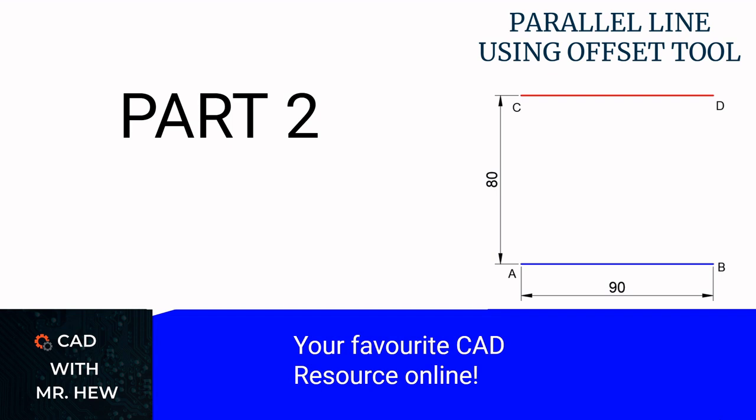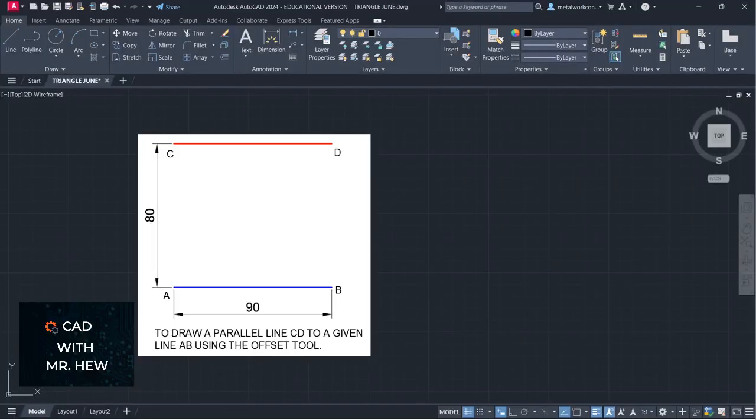We'll be starting part 2, and we'll be looking at how do we draw a parallel line using the offset tool. We'll be starting the video now. All right, so we'll be looking at the second method to draw a parallel line. So we're going to start off with our line. We're going to turn on snap and ortho.